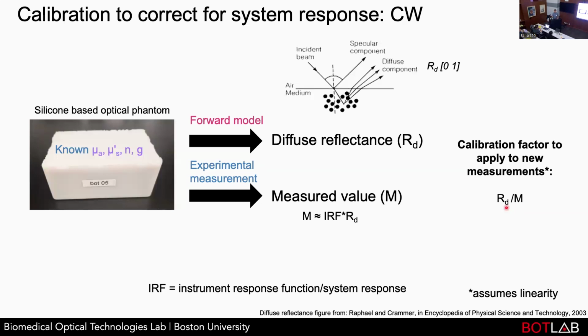It's unique to each device. Often any instrument will be linear over a certain range, and outside that range you'll see nonlinearities, which you can potentially correct for. Most CCD detectors or photodiodes become nonlinear as you get close to zero counts, and as you get close to saturation there's a roll-off. So you either use that detector in the linear range or do some kind of nonlinear correction to squeak out that extra performance. Another related question is, how long does your calibration factor last?